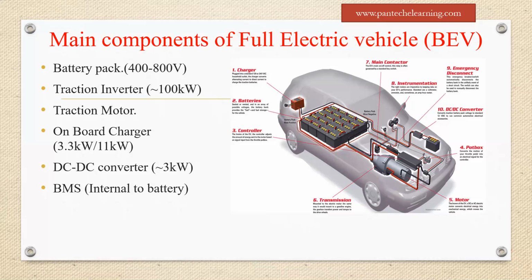You need to develop the control system. So by observing all these components, how you can build and what range they are fixing: 400 voltage to 800 voltage. If you are using a battery type of electric vehicle, the battery capacity you may fix here is 40 kilowatt hour up to 70 kilowatt hour of battery backup also.